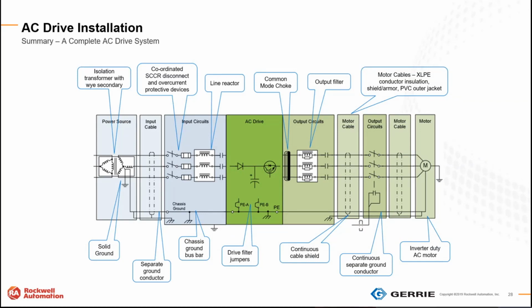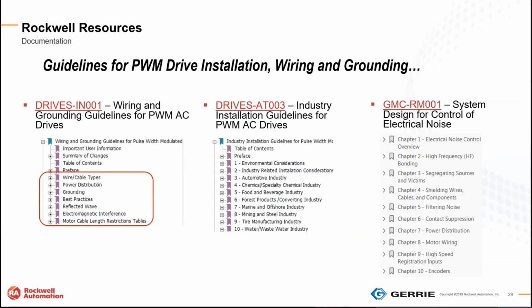How do we properly ground within that box? We typically don't really think of it that often, but it's starting to become an issue more and more that I'm finding. And then, of course, the motor itself properly grounded, and then the type of motor, is it VFD rated or not.